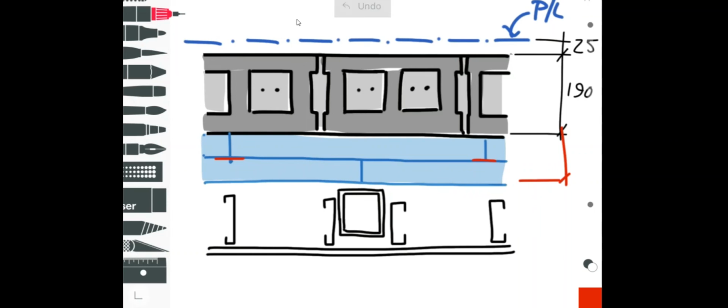And I've moved the steel in a little bit more, obviously, to accommodate that insulation so that I'm not reducing the insulation at the column. So you have to check if that's going to be doable. So there's the steel column right there, the HSS column. And then I've built a stud wall around that and put some gypsum board on there.